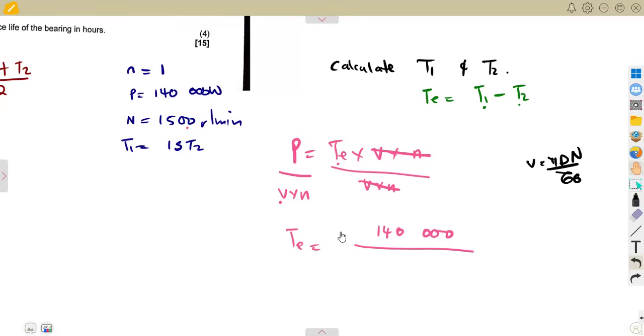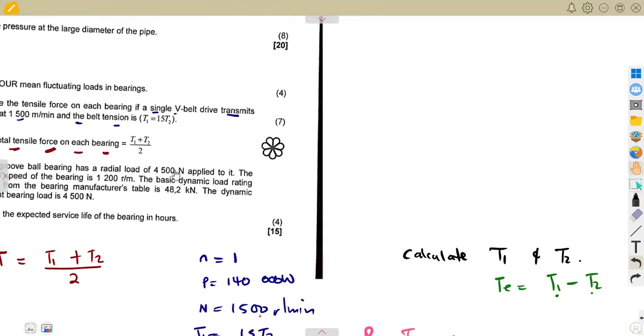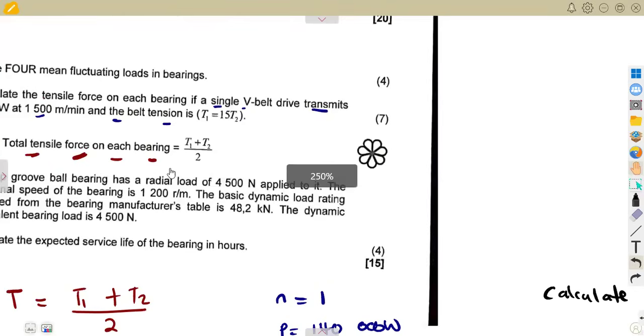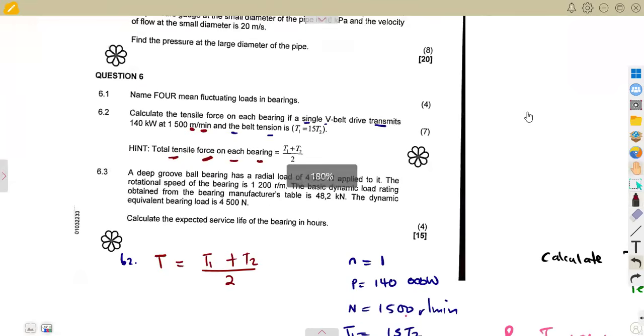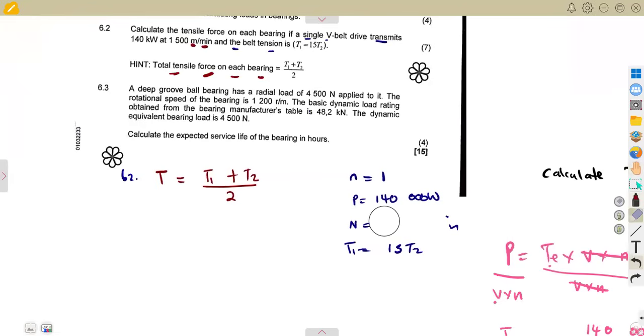There's something that I did not take. I'm considering that my working is different. This was not revs per minute. I did not notice that, because it can be like that. You can be given meters per minute. If you're given that, it means you need the velocity in meters per second. They do not want us to have many calculations. According to this unit, it's meters per minute. So it's not V. I took it wrong there. This is revolutions per minute.